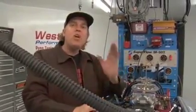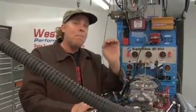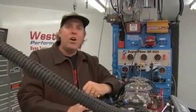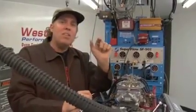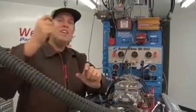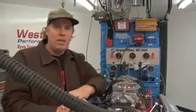Think of it this way. We always want peak combustion pressure to happen at the same point in the piston travel, say about 10 degrees after top dead center on the power stroke. Now let's assume that there is a fixed amount of time between when the spark plug fires and when that point of peak pressure occurs. So if that is a fixed amount of time, you can see that as engine RPM or speed increases, you need to ignite the spark sooner so peak combustion happens at the same place regardless of engine speed.